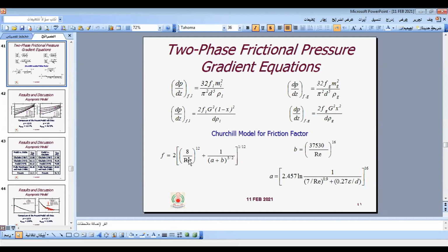And in my book chapter that I showed at the beginning of my talk, and how you can download it, I cover different models for calculating friction factor. Also, I show how to calculate the friction factor equation for different shapes. For example, in the book by Shah and London about heat exchangers, published in 1978, there is one famous correlation to calculate friction factor as a function of Reynolds number and aspect ratio for rectangular shape.